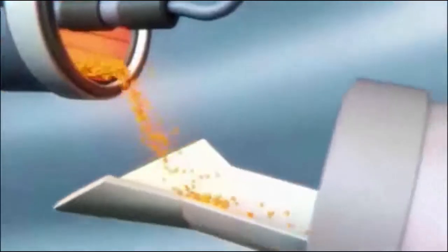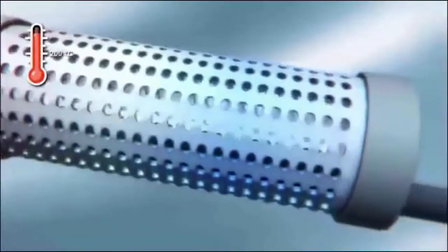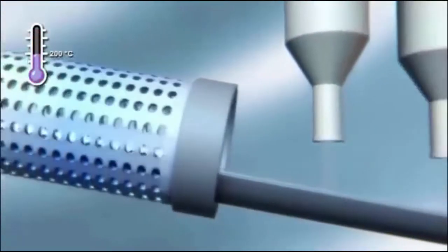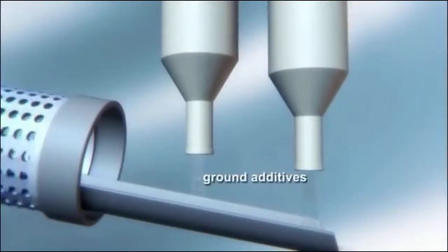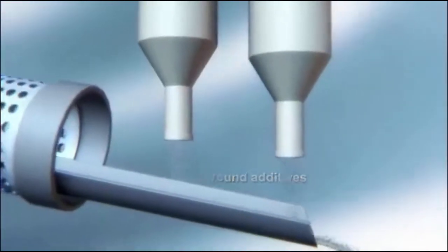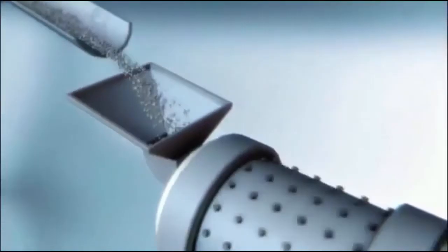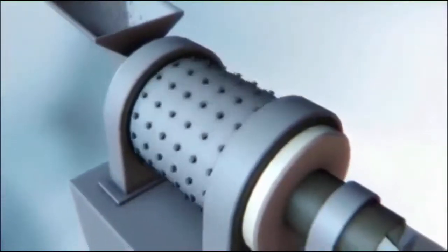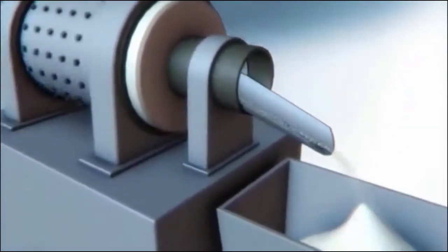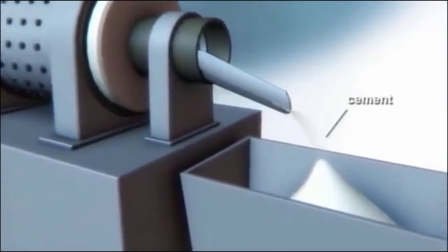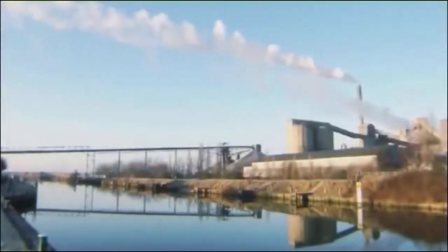After the incineration process, the cement clinker drops out of the kiln and is cooled to about 200 degrees Celsius in a grate cooler. After adding gypsum or anhydrite and sometimes further ground additives like slag, fly ash and limestone, the clinker is ground in mills to produce fine cement. The quantity and type of the additives influence the chemical and physical properties of the cement. The cement is stored in silos and is mostly supplied to concrete manufacturers as bulk material for further processing.